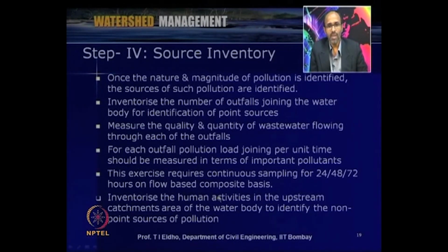Inventorize the human activities in the upstream catchment area of the water body to identify the non-point sources of pollution. So once we identify the pollution source, we have to identify whether it is a point source or a non-point source of pollution, and then again we have to continuously monitor and take samples and look at where it is coming from and how the movement is taking place, so that we can go for various measures.